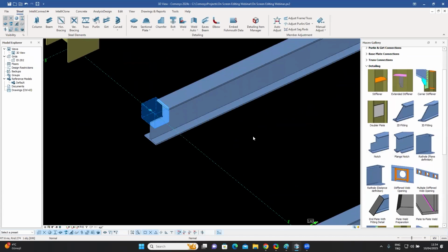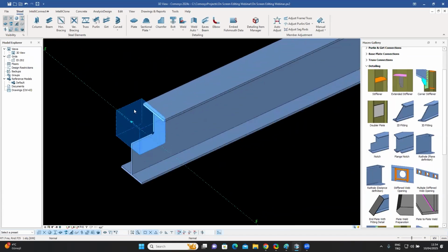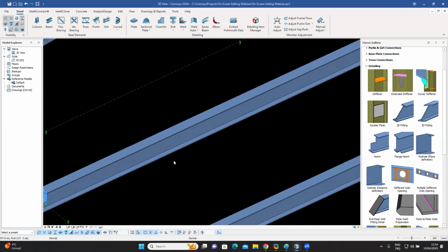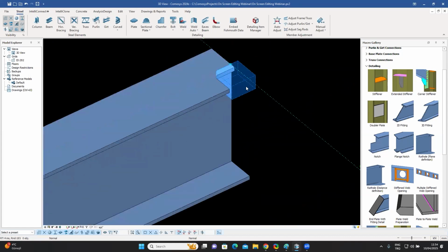These are little detailing macros. And these two now have their own little handles. So when I do a little notch over here, it actually comes in with the exact parameters of the notch, which I can then go in and say, I want 150, and I can say apply, and the notch is modified accordingly. The same thing is obviously possible with the flange notch parameters as well.